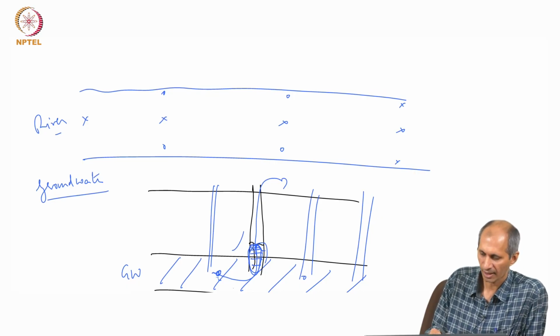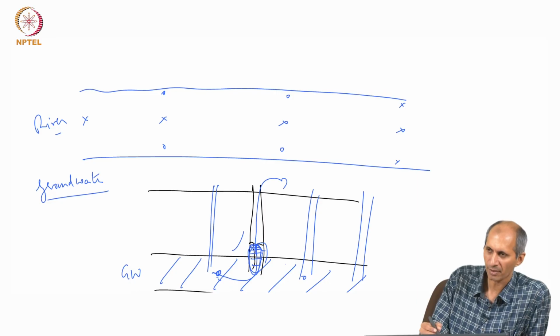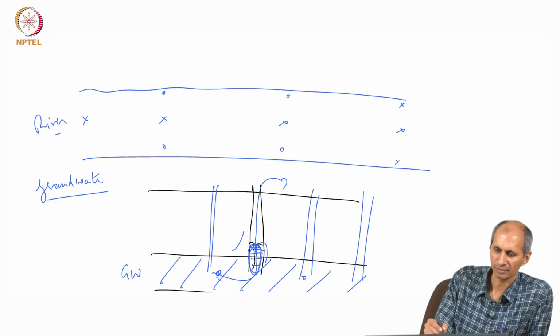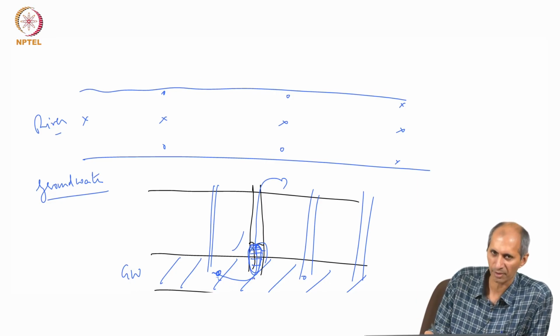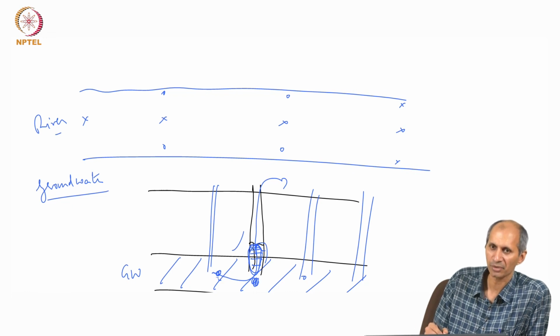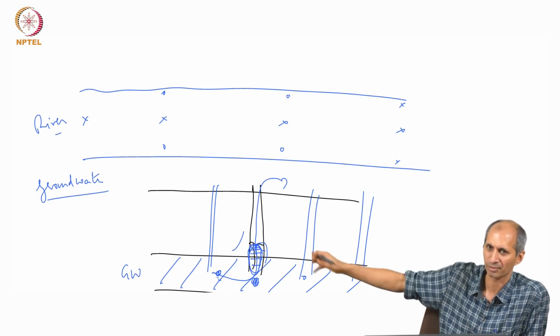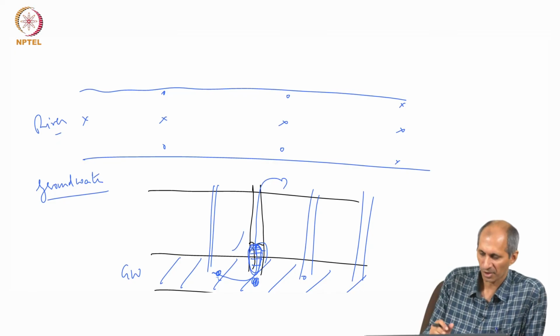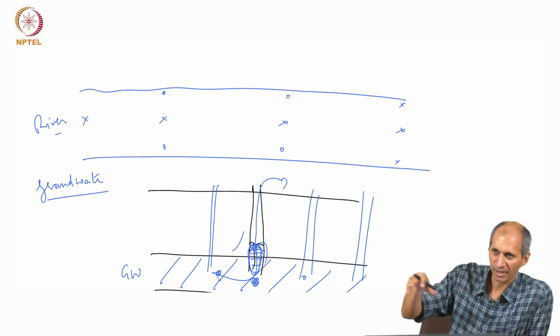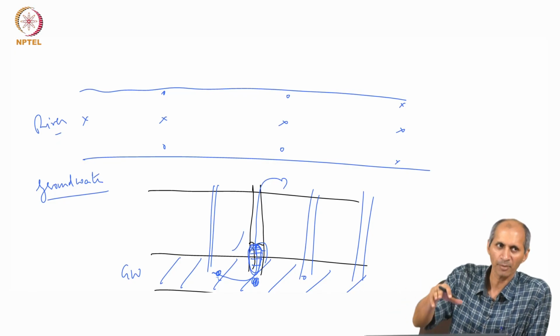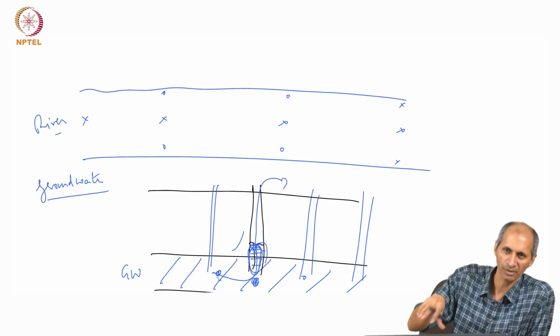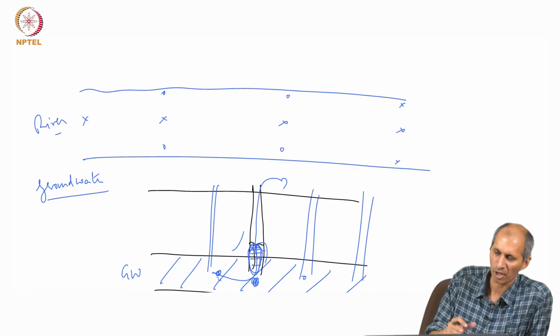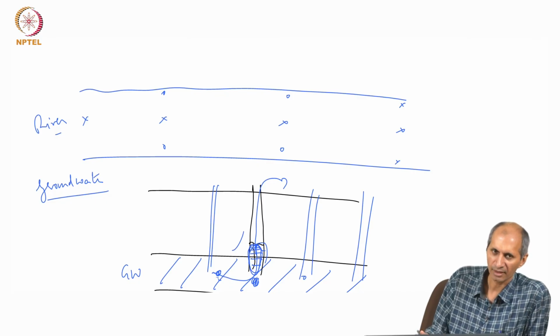If you are looking at the same question that we asked in the river, where is the source? Groundwater here is polluted. You have to find out where is the source. The source can be anywhere. The groundwater is not like a river, a small flow. It can be a large section that is floating around. So, you have to go and make wells in a given area and then make a map of the concentrations and then figure out where the source could be. And it is much more complicated. You have to understand the hydrology, and this is where the analysis of transport comes into question.